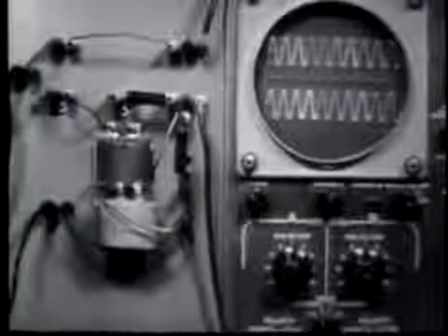Now here's the series tank in the series position. Inductor, capacitor in series. And the parallel tank in the shunt position. It's our parallel tank inductor, our parallel tank capacitor. Let's see how this combination affects our output signal. As you can see, the circuit is functioning as a band-pass filter. Now notice the good attenuation of those frequencies off resonance and the sharp response of the filter at resonance. Now this is due to having two tanks providing the filtering action.